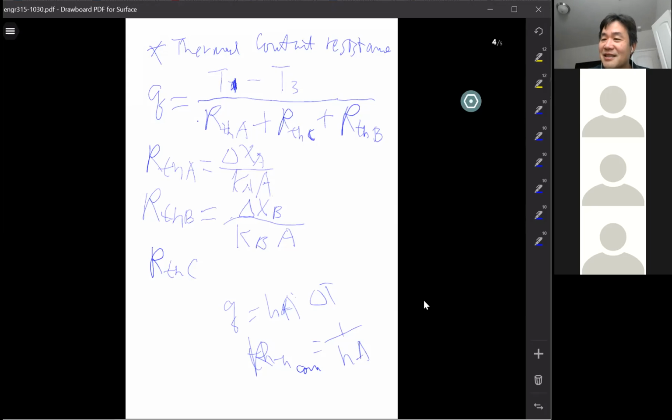That's why it's dT over dx. There's a derivative in there, right? It's more like an analytical solution. For convection, it's too complicated. It's flow dictated, and the flow is so complicated. You cannot solve the flow equation that easily. You don't have the equation for convection. That's why engineers created this equation. They know Q is related to the delta T, to temperature differences, right? So why not just put in a coefficient, h, times the area. Also, they know Q is related to the area, how much area is exposed. They know it's related to the area and to delta T, but they don't know the exact relationship.